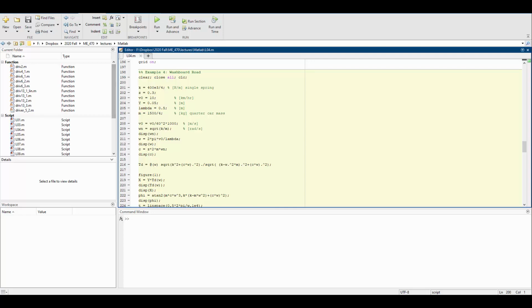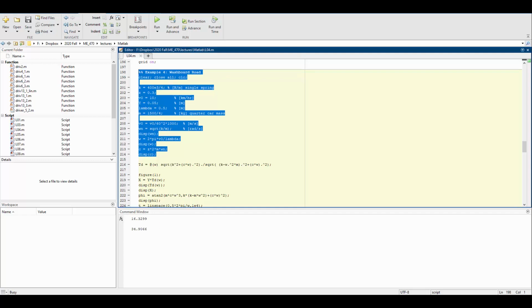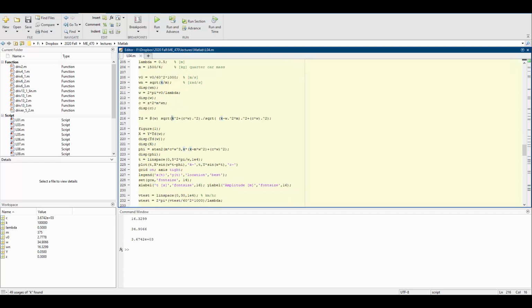Now we can go into MATLAB and graph what the response of the cabin is going to look like on this washboard road, putting in all of the pertinent information that we already solved by hand. We'll come back to the transmissibility in a moment. First, let's just plot the response of this system when we were going at the rate of 10 kilometers per hour. So we can calculate our X, and we can calculate our phi, as we've already done. And let's look at what this does over 5 forcing periods. So that's 5 times the 2 pi over the omega will give us 5 forcing periods.